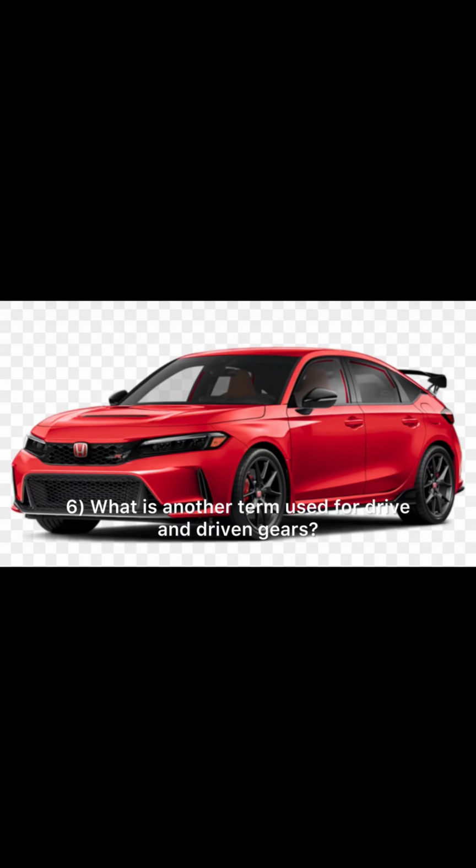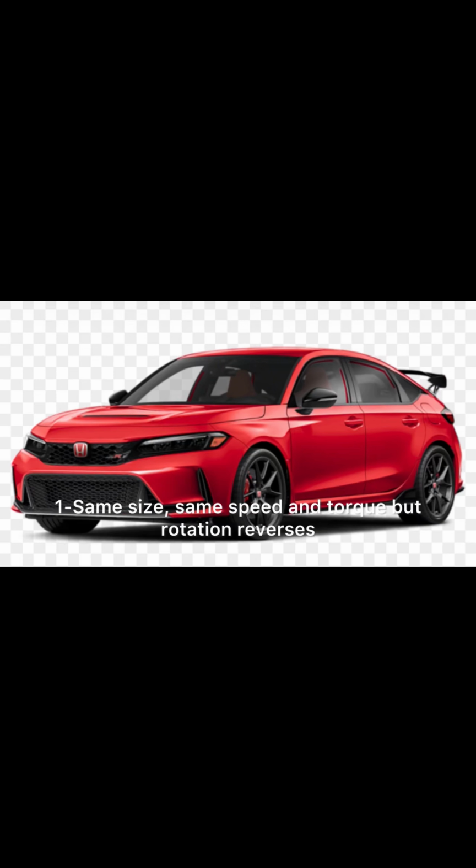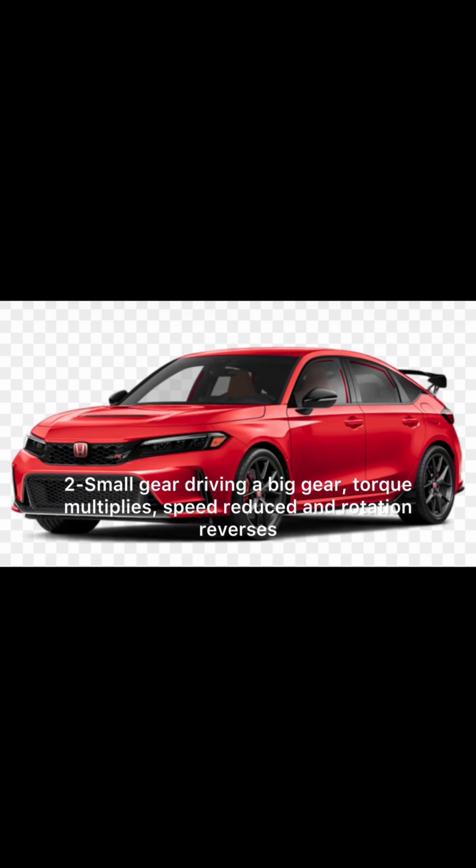3. What is the center point of a gear to its outer edge referred to as? Radius. 6. What is another term used for drive and driven gears? Input shaft and output shaft. 7. What are the three-part principles that govern the relationship between gear size, torque and speed output? 1. Same size, same speed and torque, but rotation reverses. 2. Small gear driving a big gear: torque multiplies, speed reduced and rotation reverses. 3. Big gear driving a small gear: reduced torque, speed increase and rotation reverses.